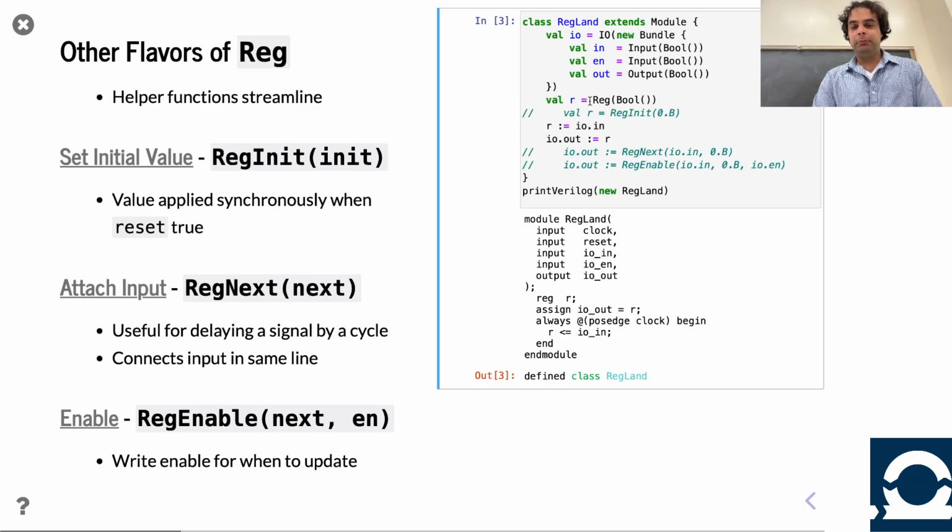Alternatively, we've seen the Chisel approach. We just instantiate Reg. Here's the hardware. We wire it up. None of this weird inference stuff. It is true that in some Verilog design environments, you can also choose to directly instantiate a register. So here at UC Santa Cruz in our logic design course, CSC 100, we have students directly instantiate the flip-flop register rather than using this always @ block. You don't see the always @ block until CSC 125, but the idea is still there. Cool. We have a register.